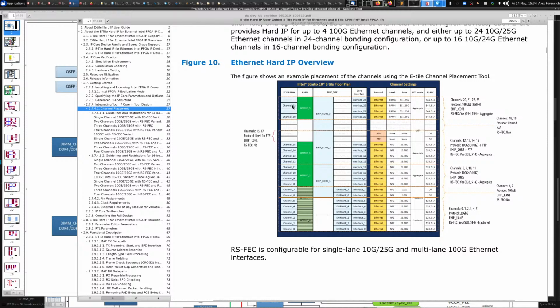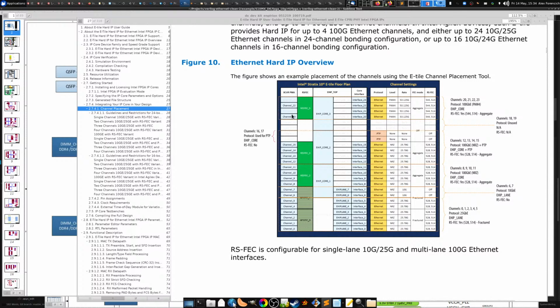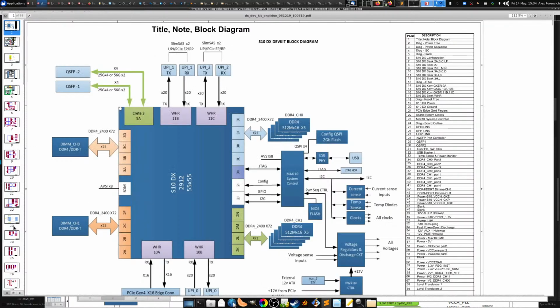So in this case, that's how it's wired up. The issue is that with the QSFP modules, if you want to use them in PAM4, you've got to use channels 0 and 1. You actually can't skip a channel on the QSFP transceivers, so when they wire it up on the board, they actually have to crisscross those channels.